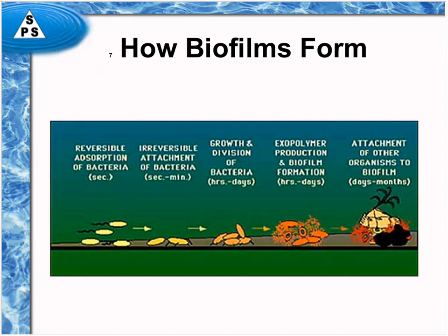Since we're more concerned about what's happening in high purity type water systems, what can happen when the flow allows, or in other words, when the flow is nearly stagnant, the water is just very, very slowly flowing, is you'll get these tall columnar kinds of almost mushroom shapes of biofilm that becomes a very tall structure.